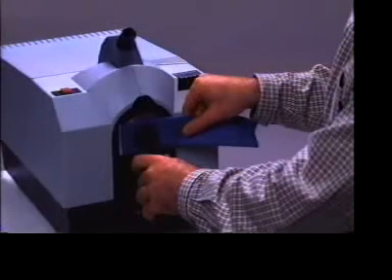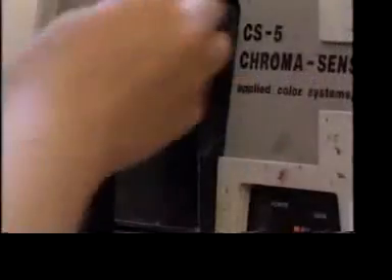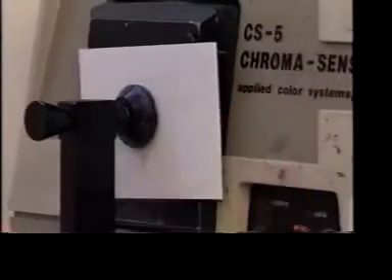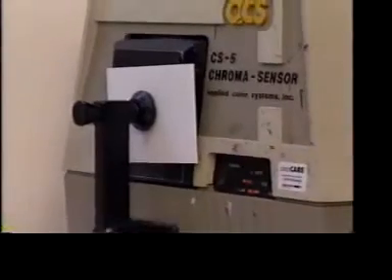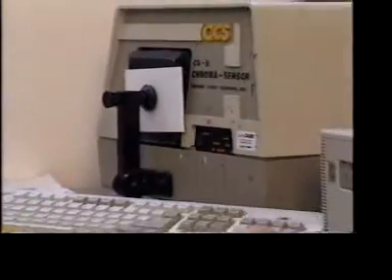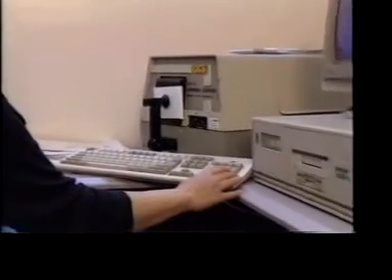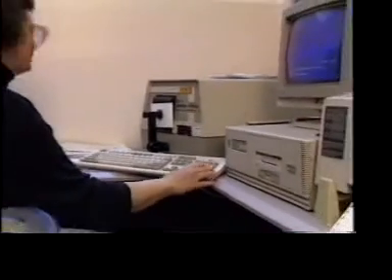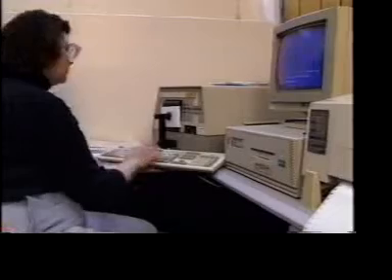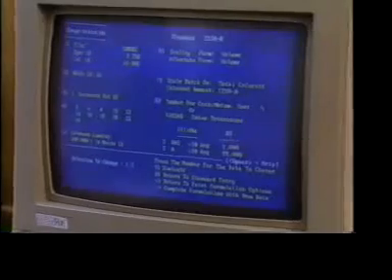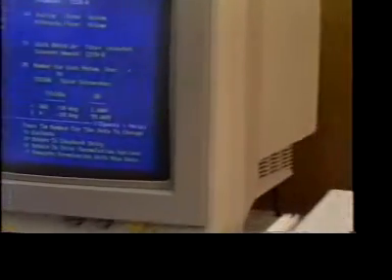Computerized color matching uses an optical instrument called a spectrophotometer to analyze and determine a sample's color. This device aims a beam of light at the sample and measures the amount of light that is reflected across the visible spectrum of light. This information is used by the computer to calculate a formula calling for your colorants and base paints to match the sample. The specified formula is then printed out, often as a label for manual dispensing, or sent electronically to an automatic colorant dispenser.